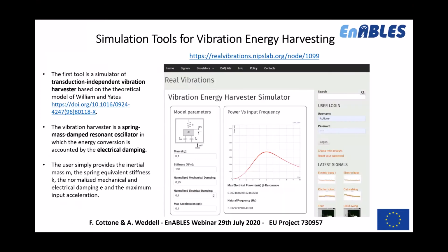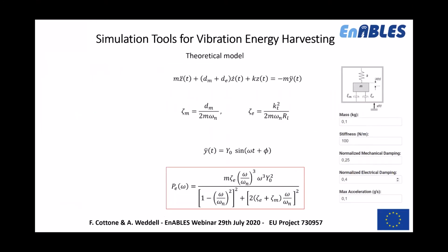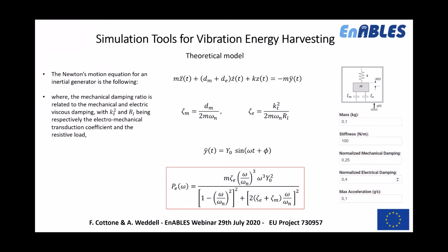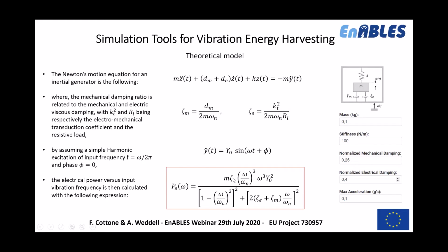Going on, this is the theoretical model used for this simulator. As you can see, it starts from the governing equation, the dynamical equation, and the mechanical damping factors. And then the excitation, this harmonic excitation in this case, going from 0 to double the resonance frequency. So the simulator provides the power response over the frequency, and the power response over the frequency is given by this formula, basically.